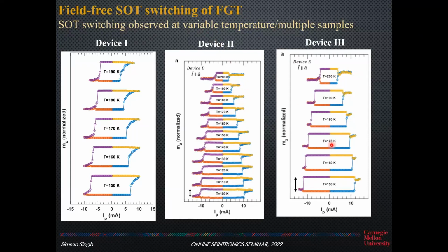Related to Kirill's question, in your device and sample variation, do you see any polarity dependence? What I mean is, in these TMDs each layer has different in-plane symmetry, polarity symmetry breaking. When you make your flakes on top of each other, you might have opposite polarity or out-of-plane torque generation, depending on the electric field current direction.